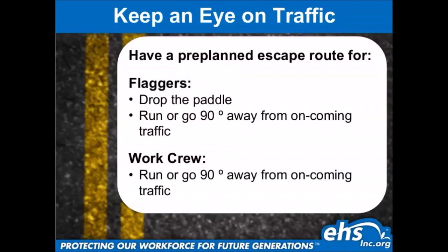You're not going to jump in the roadway and try to stop the car. You're car versus person, car always wins, all right? So flagger, what you're going to do is drop the paddle and run away from traffic. Again, flagger isn't just going to run away. He also has to warn the guys working behind them, right? Because if it can hurt the flagger, it can most definitely hurt the guys working behind him.